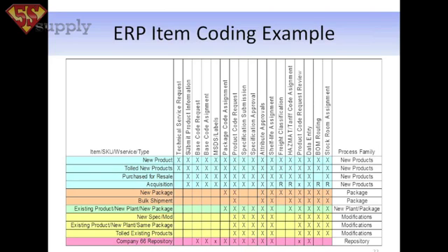Okay, so here's an ERP coding system. You saw that. So it has the different things that they have to do across the top. But if you notice, not all of them have to go through the same steps. So you see a big gap in this area here. None of these go through this. There's a little gap here and gaps here, so they said, hey, that's close enough. Now, if you notice, this one has an X above it but doesn't below, but they said, once again, that's close enough. We can live with that. We can use that as our process family matrix, and it'll be fine.